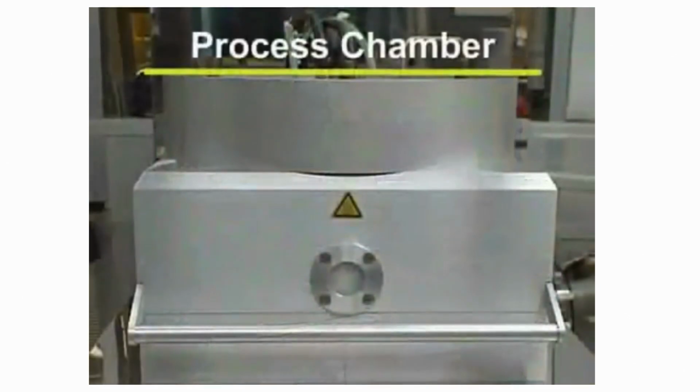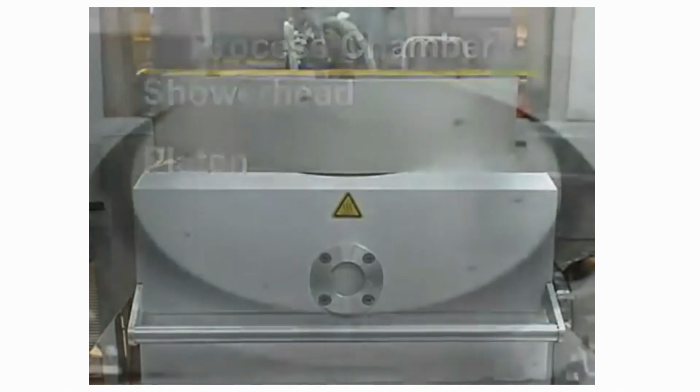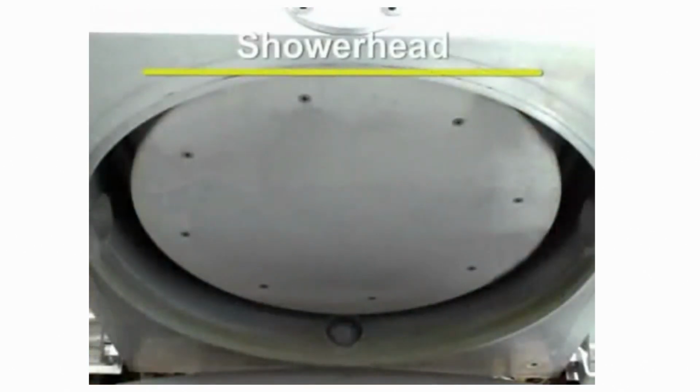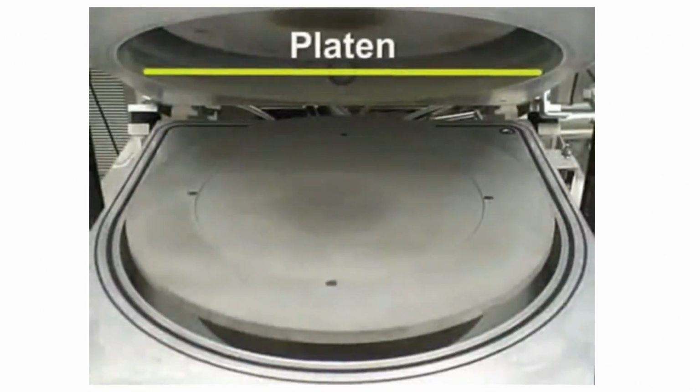The process chamber is where all the processing takes place on the system. The two main parts of the process chamber are the showerhead and the platen. The showerhead is used to evenly distribute the gases in use during processing. The platen heats the samples to improve the deposition quality and increase the deposition rate.